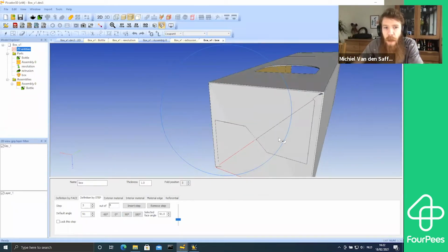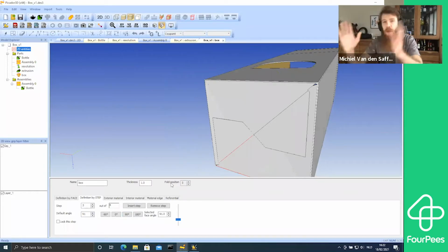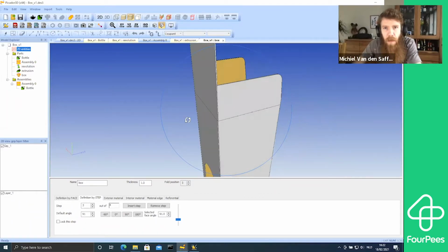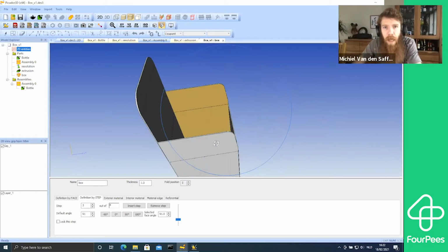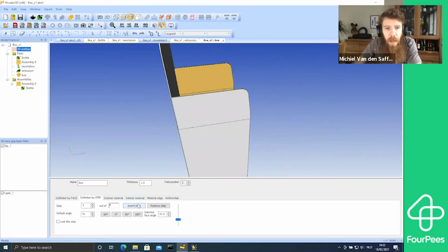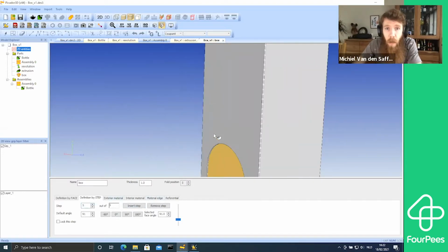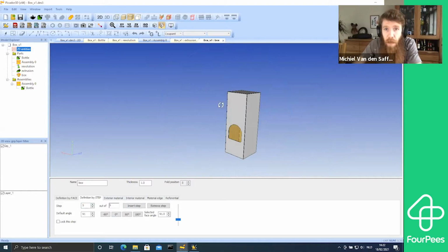Of course, now if I play that step in the animation, it'll just fold them all at the same time. But that's a bit difficult to do properly. So then I'll turn my box upright so I can have a look at the top, and I can add some extra steps. I'll insert a step where I fold these flaps. Actually, I don't have to because I already have a step 5 where the whole thing is folded up. So now I have a step-by-step folding animation for my entire box.